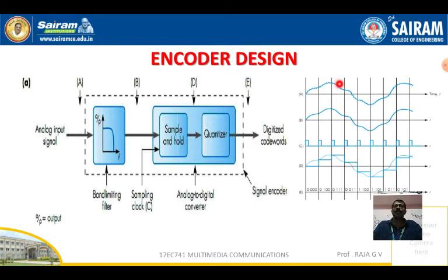The name itself implies that it is used to sample the amplitude of the filtered signal at regular time intervals, and to hold the sample amplitude constant between the samples. This in turn is fed into the quantizer circuit, which converts each sample amplitude into a binary value called a code word.